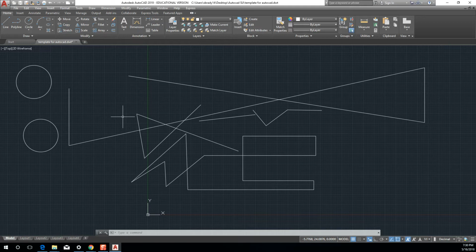But the problem you get into is that, hey, I've generated all this stuff on my screen. How do I get rid of it when I don't want it anymore, right? Well, I can select objects and I can delete them in model space, right? So you can initiate almost any drawing command in here, do whatever drawing you want to do. And then if you want to get rid of some geometry, you can click right on it, click, right? I'm not doing anything with my mouse now. I've moved my mouse away.